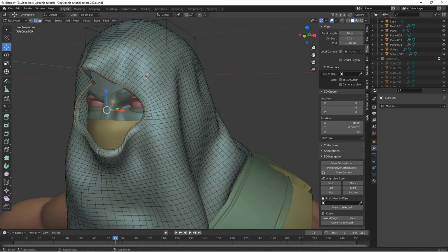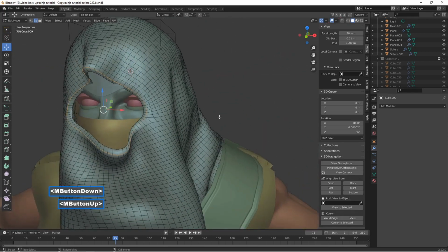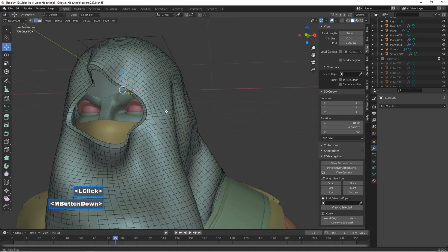So I have this line here. The bevel's going to split this line into three with what I'm going to show you next. I have this here. I'm going to press C to deselect. I press C, held the middle mouse button. I had one edge there selected to deselect there. I'm going to hold Control, press B. Then I'm going to hold Shift. Shift lets me have fine selection. So I put a double line, and I'm going to roll the mouse one time. Left click to lock that in. So now I have this hard edge with that thickness. That's what I wanted. I want this to not intersect there.